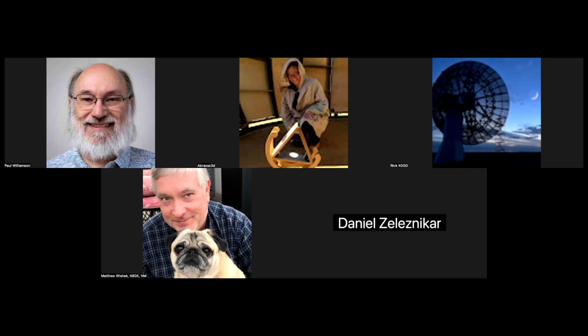The basic idea of the hack. I'm calling it a hack. They presented it as a vulnerability, a cybersecurity sort of issue. Is that if you can modify the coefficients for the shaping filter, for your transmit filter, like a sinc filter or whatever, if you can change that, then you can have a covert channel. Now, this assumes that you also have some way to get information in, orthogonal to your main signal, and you're going to have to settle for a much smaller data rate.